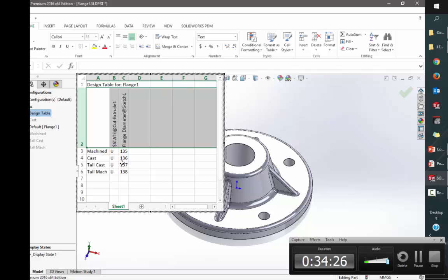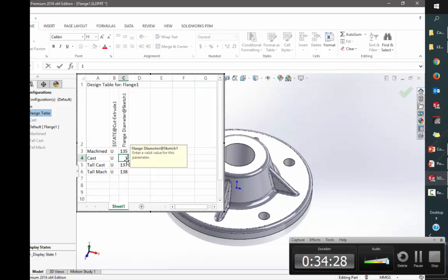All right, so I'm going to go ahead and fill in the machine information I needed here. So this will be 135. We were taking this to 150, taking this to 150, and then I have to work with the U. Okay, U stands for unsuppress. It means it's showing. I need to suppress these holes out. So what do you think I put in for that? S, right? You can also use ones and zeros. You can also use S's and nothing. There's a couple choices that you have. Just don't get too fancy. And actually, when I pick on it, you'll see what is allowed in there and not allowed in there. All right? Everything looks good to me here.